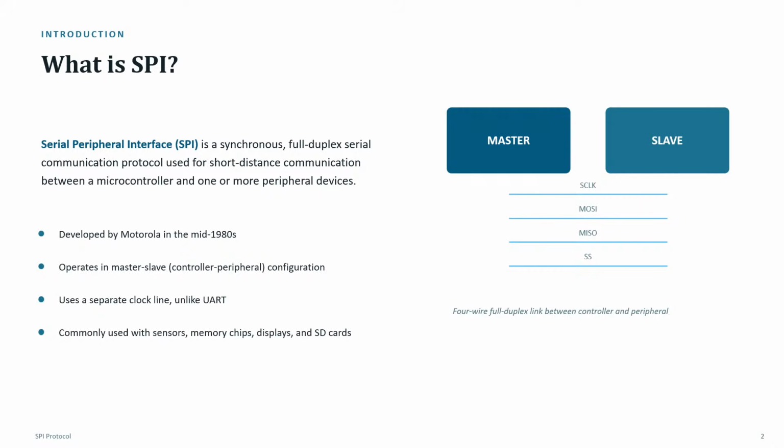First of all, let us discuss the SPI protocol, where SPI stands for Serial Peripheral Interface, used for connecting with peripheral interfaces. It is a serial peripheral interface protocol and it's a synchronous protocol. Why is it synchronous? Because the master provides the clock to the slave, and both master and slave work with the same shared clock. It's full duplex. It's a serial communication protocol, in the sense that you send the data one bit at a time, on every particular edge of the clock.